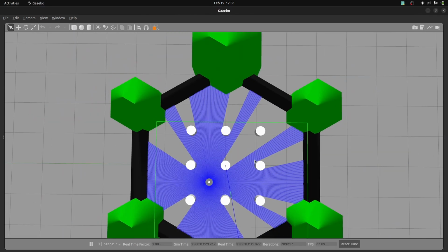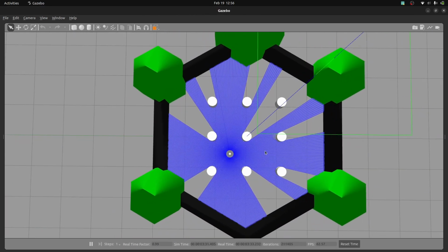As you can see, the robot has passed through all of the goals. You can plan it to perform very amazing projects. I really enjoyed it when I first saw this multi-waypoint robot following in the map. Sometimes we have to make changes in the global costmap and local costmap, but it still works, and otherwise recovery behaviors start to work. The thing is, with Nav2, integration of autonomy into a robot is becoming really easier, in simulation and in the real world as well. I will give an example of that as well.